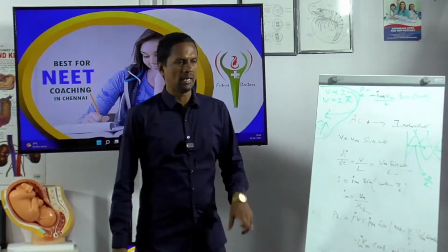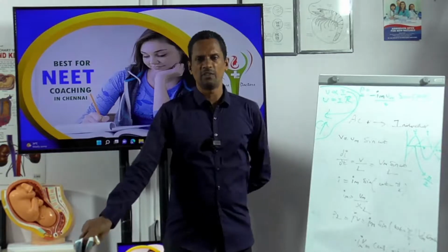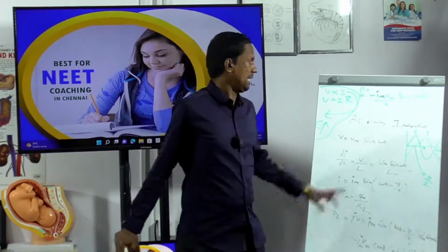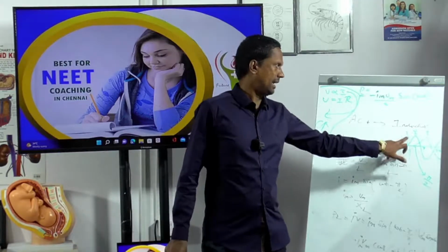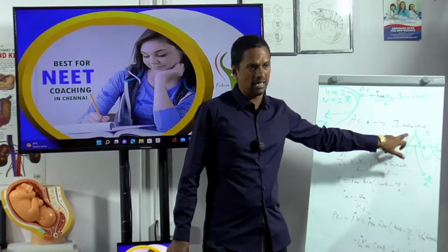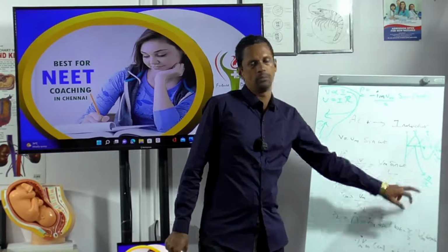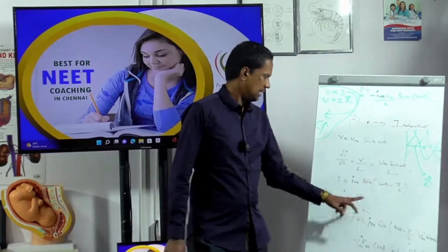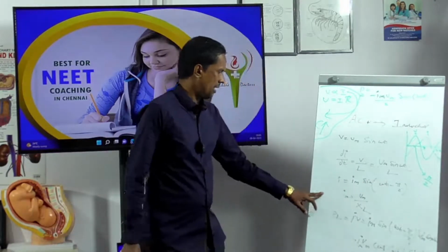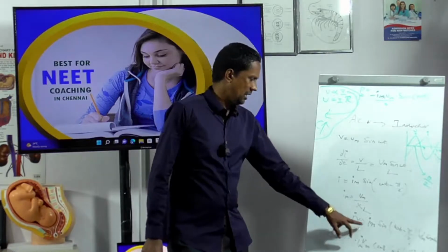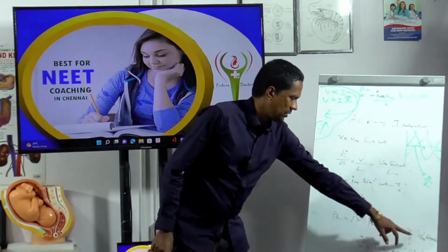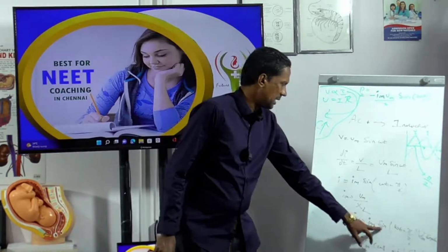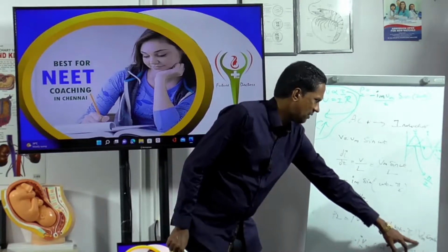That means voltage and current. What is the difference between voltage and current now? Pi by 2 in an inductor. In an inductor, the current and voltage travel with a difference of pi by 2. So PL is equal to I times V, which is Im sin omega t minus pi by 2 into Vm sin omega t.